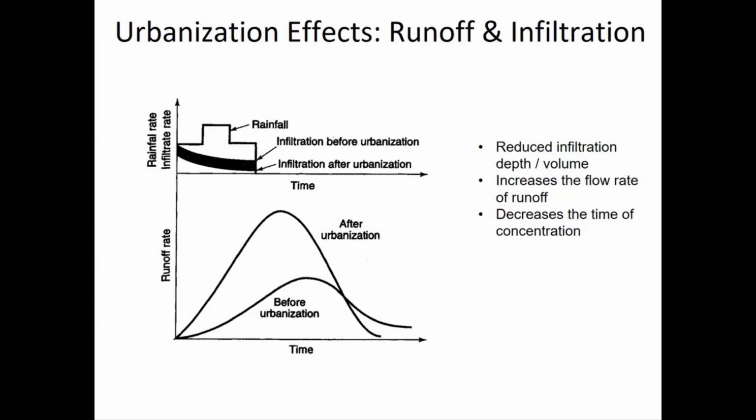So if you live out in the countryside and it somehow seems like the creeks are higher than they used to be, it could be that there's development in your watershed. The reason is there's less infiltration, and for the same amount of rainfall, there's going to be more rainfall excess.